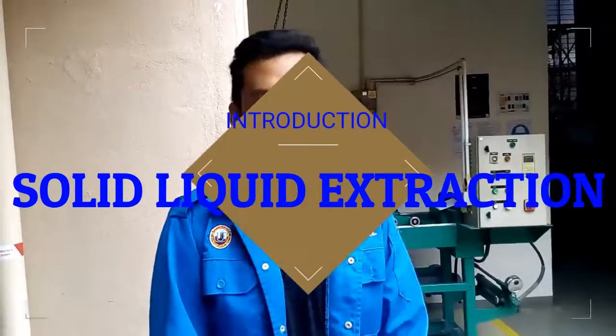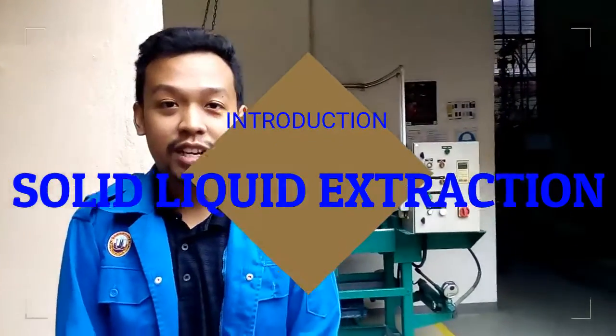Very good afternoon. Right, first we will talk about solid liquid extraction. Solid liquid extraction is similar to LLE, which is liquid extraction, except that the solute is dispersed in a solid matrix rather than in a carrier liquid. The solid phase containing the solute is dispersed in the solvent and mixed. The solute is extracted from the solid phase to the solvent, and the solid phase is then removed by filtration.